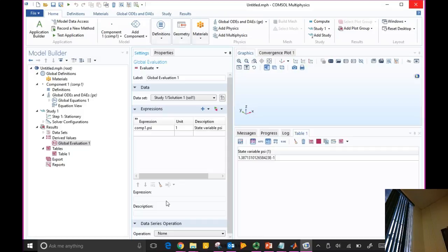Okay, so what it has to do is guess at T, get all the k values, put them into this expression, right? And then solve and see whether the function is 0. So instead of guessing on psi and iterating, it guesses on T. But every time it guesses at T, it goes and finds the k values because I have given it the expression of how k changes with temperature. Right? Now I can do the same thing with pressure. K is a function of pressure. K is actually a function of both temperature and pressure.